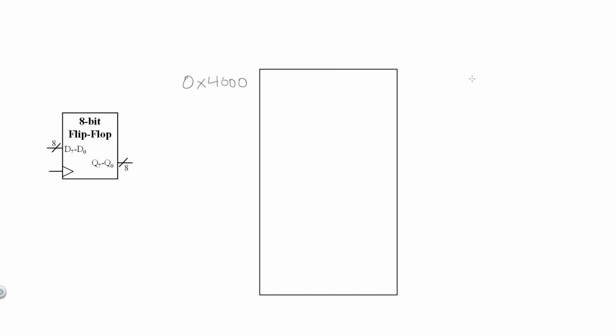Partial address decoding is when not all of the address bits are used in the address decoding, and therefore act as don't cares. So with respect to the output port, because none of the address bits are connected directly to it, all 24 of the address bits would have to be used in the decoding logic for it to classify as being fully address decoded.